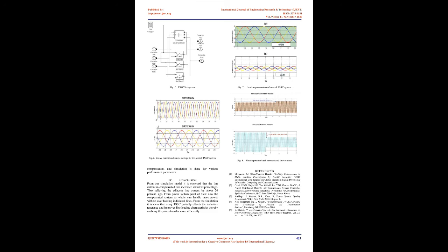TSSC implementation and performance analysis. Figure 3 shows the thyristor switched series capacitor, TSSC. In this device, the thyristors should be kept untriggered so as to connect the capacitors in series with the transmission line. If the thyristors are turned on, the capacitor is bypassed. Thyristor turn on must be at a zero voltage condition, ZVS, as it occurs in the case of the TSSC, to avoid current spikes in the switches.